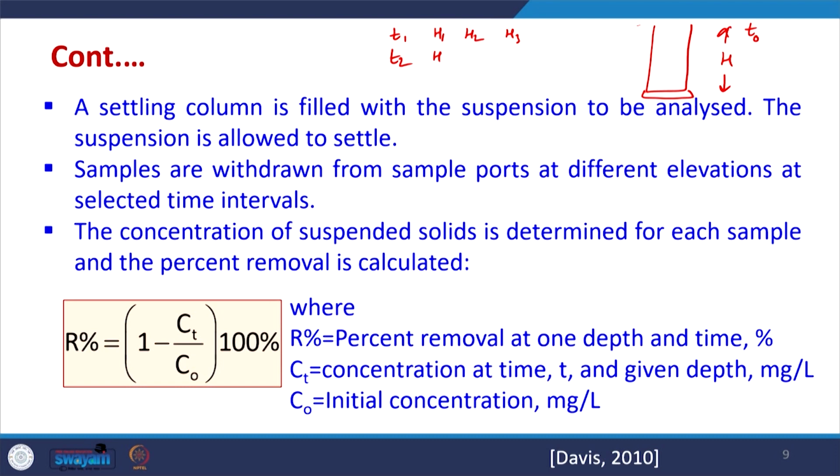And since we know the initial concentration and the concentration after some time, we can calculate the percentage removal efficiency at various heights at some particular time. After that, again the second time will be there. So, we will calculate the removal efficiencies at different times and heights.